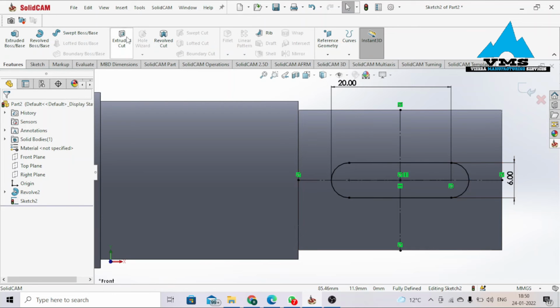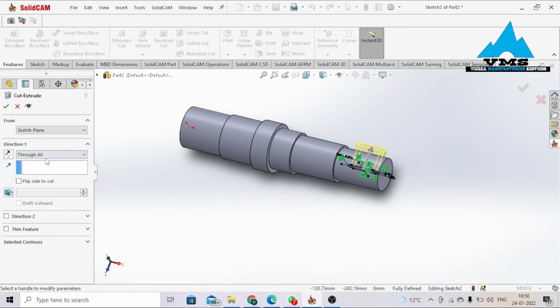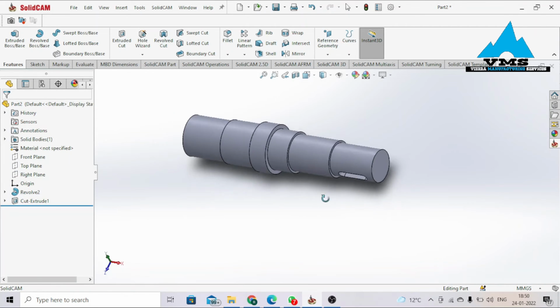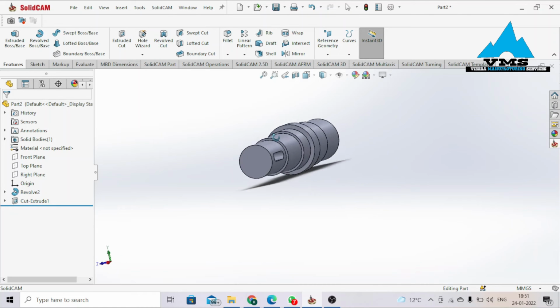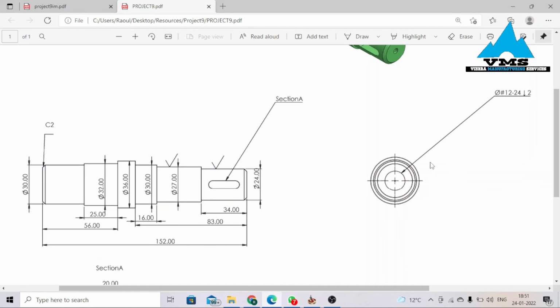I'm going to extrude cut all through. I will just take it all through. Doesn't really matter to all, but okay, fine. So here we have this, right? Okay, so looking at the diagram, we got a hole over here. So anytime you see this sign hash inches, I'm going to be using an inch hole, and I'm going to extrude by 2 inch downward.